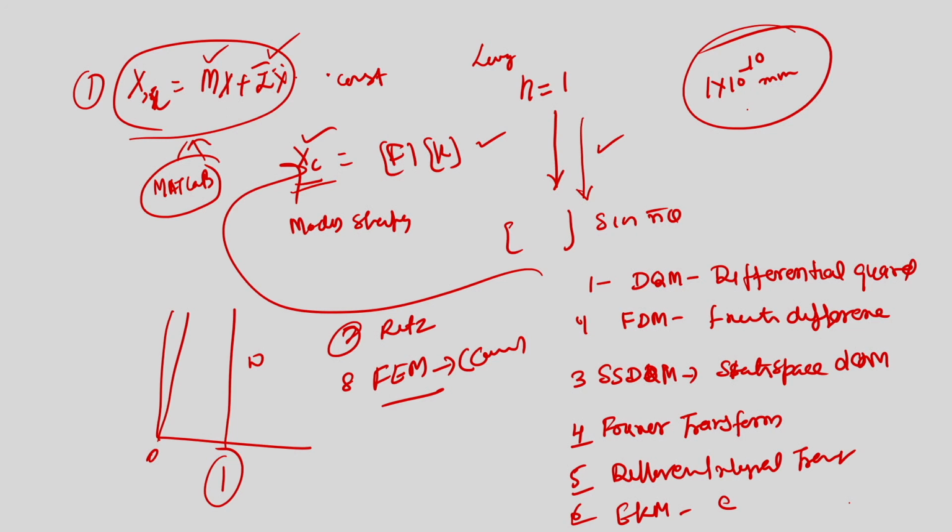The only issue is that we have to prepare accurately the matrix M, the matrix I bar or the matrix Q n bar; the rest of the part can be taken care of. So, in this way we can solve a Levy type cylindrical shell or an arbitrarily supported shell using the EKM technique or the Navier type. So, the static and free vibration problem is solved.